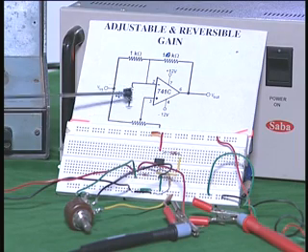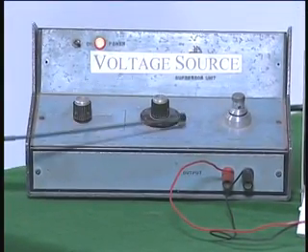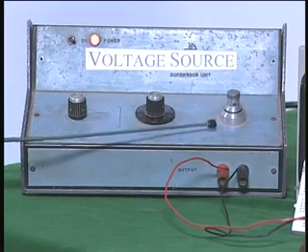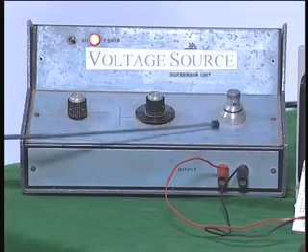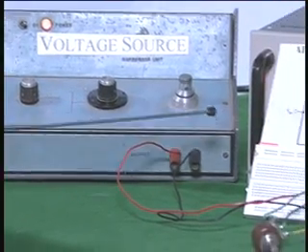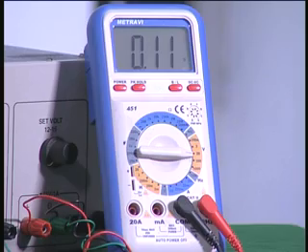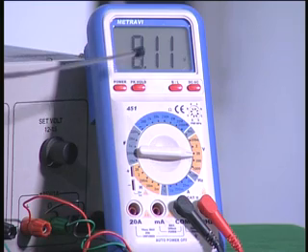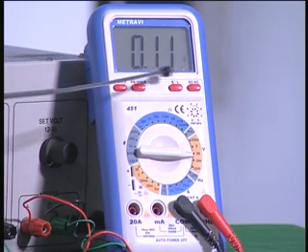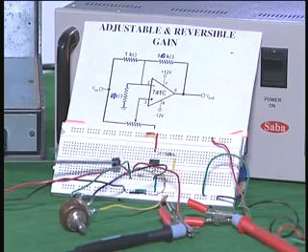n is 10 here. Now I have taken the input from the voltage source here, which we have already seen, and what I have done is I have reduced the voltage by 10 times to the previous value. Previously it was 1 volt in the earlier experiment, now I have kept it as 100 millivolts, 0.1 volt. So that is what you will observe now, because I have connected the multimeter at the input terminal. If you look at the multimeter output now, it shows 0.11, that means 110 millivolts. This is 0.11 volt or 110 millivolt approximately. So that is the input voltage. Now what I am going to do is take the multimeter from the input and connect it to the output. See what happens.